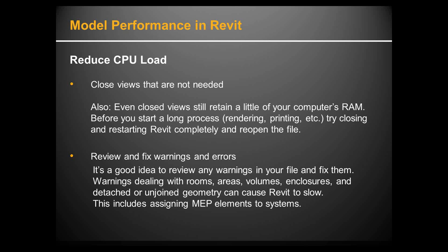Close hidden views, and even if you've closed them, it still retains a little bit of sticky memory in there. So before you start a long process, if you know, okay, this is going to really stress out my computer, rendering, printing the whole set with everything loaded, close Revit and then restart it to clear out that sticky RAM that Revit is still hanging on to.